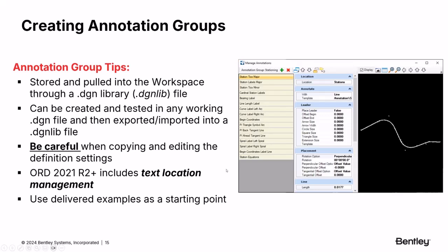So the point being, if you copy an annotation group, that doesn't make a copy of the individual definitions themselves. So the standard workflow is to copy the group and the particular definition you're trying to adjust, so that you're not affecting any other groups that might be using the same definitions.